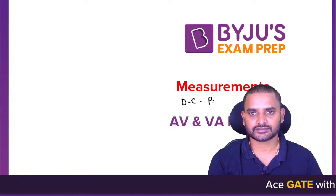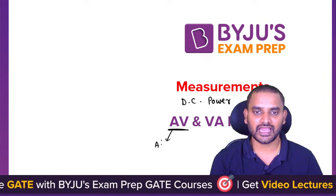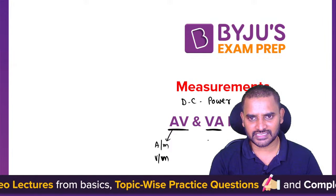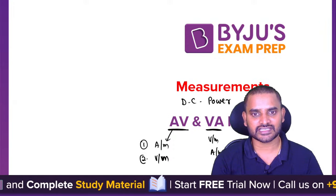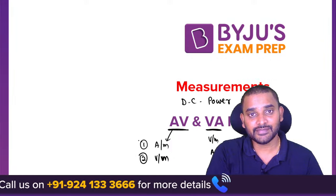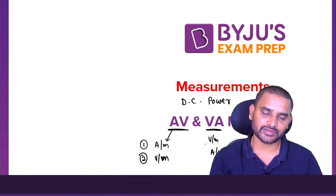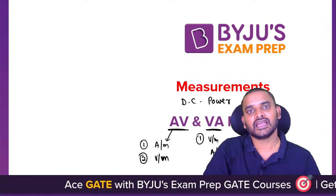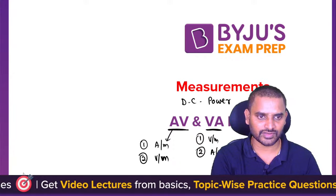DC power measurement. Here the AV method is nothing but ammeter and voltmeter. The VA method is nothing but voltmeter and ammeter. Which means in the AV method, if you start from the supply side, the ammeter is connected first and then the voltmeter. Similarly, in the VA method, after the supply, the voltmeter is connected first, and then the ammeter. Or otherwise, in another way also we can say.